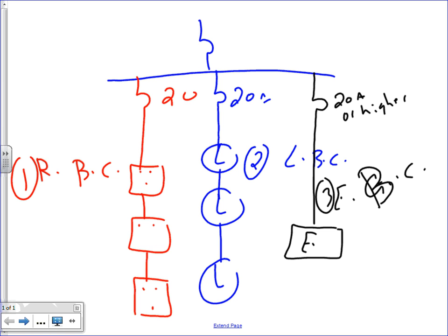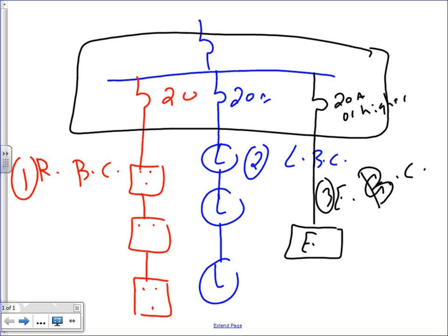All coming from the panel. The most important thing that you have to understand, this is all coming from one single panel. Now, let me just talk about this. How many conductors do we need to carry 20 amp circuits in a conduit? 2. So here's my conductors. 2 conductors, number what? 12, thank you.